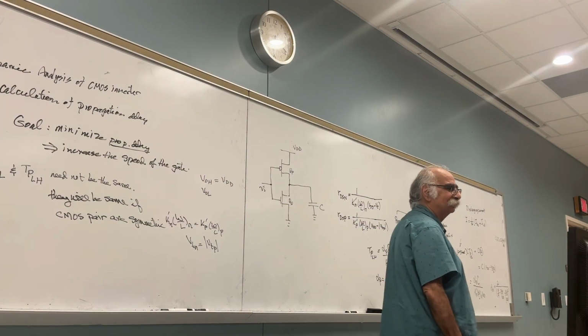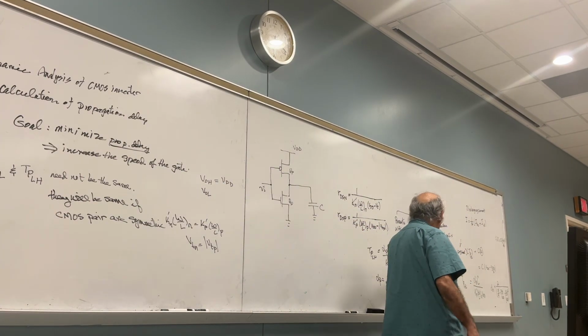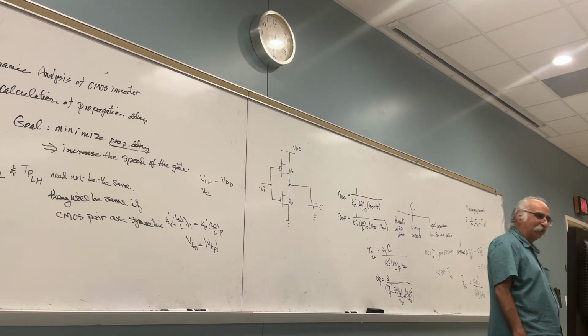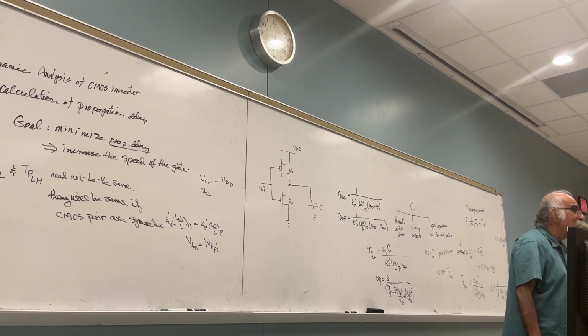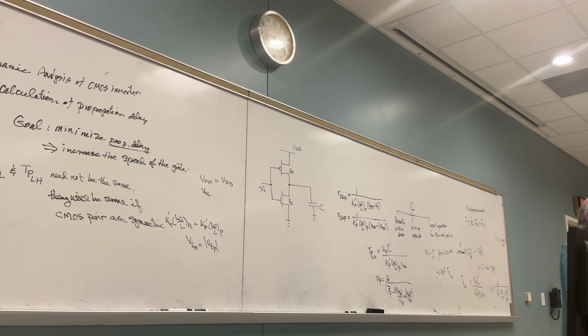How about VDD? Do I want to increase it? Yes, I want to increase VDD. Dilemma. What is it? If I increase VDD, I'm going to increase the power dissipation. Yes or no? The trend is to go lower in VDD. You follow me or not? To conserve the batteries.